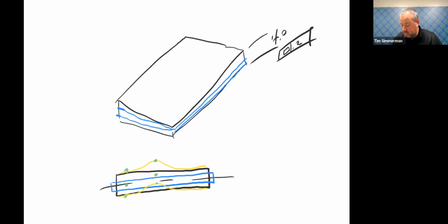Sorry, say that again, Francis? That means you would definitely use a max inscribed instead of a best fit when you're creating that feature on your CMM. Could be probably a bit advanced for what we're trying to talk about today, though. Francis is talking about some of the CMM programming that we can do. Oh, the max inscribed would give you the fattest result, where the best fit gives you an average of all the points. Okay.